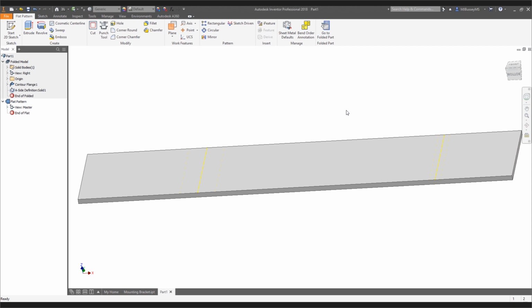Now, if you're actually experiencing a different radius with the same tool, you're most likely going to have to run some experiments on your tooling and your manufacturing process. And the way to handle it in Inventor is that for each of those types of bends, you have to assign that particular bend a different unfold rule. Unfortunately, Inventor can't magically determine what a K factor is. I would love it if it could, but it can't.